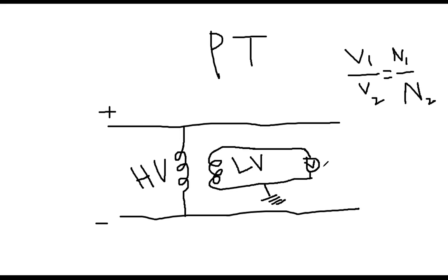And because this is the line going on, you have to assume that the loads are connected here in parallel, between this line and the neutral line, so you can connect a transformer to measure the voltage. The condition is that the point where the technician, lineman or engineer goes, they will measure the voltage from the low voltage side, and then by using this equation, they will find out what the voltage was here.